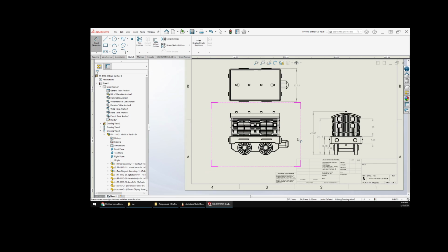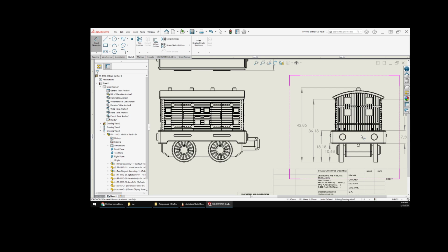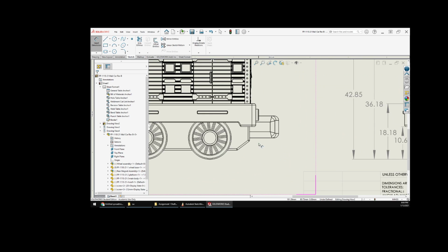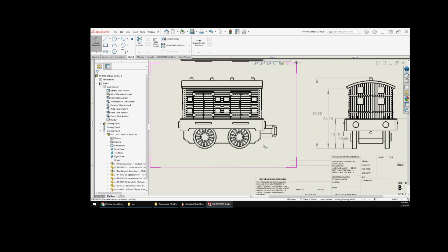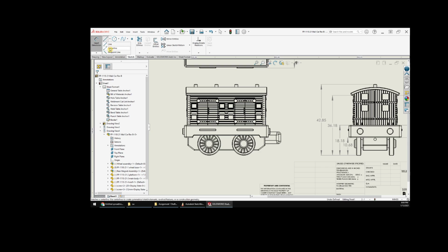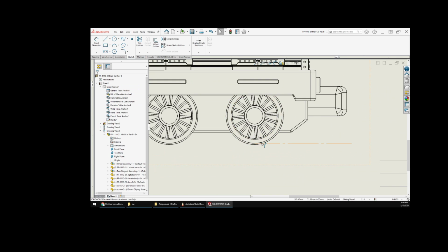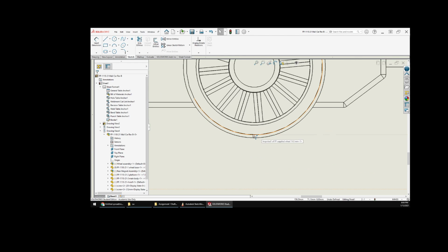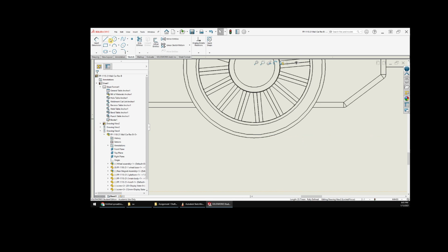So basically, the rest of the dimensions, maybe... All right, that's that other side. So maybe a couple dimensions here. Again, you can see I can't grab that. But since I'm doing a few control dimensions, let's draw a line in there. And what I'm doing is... Oh, well, here, let me show you this. Make sure you grab the right point. You can kind of see I grabbed the wrong edge. Well, that's going to be a big problem because my dimensions are going to be off.